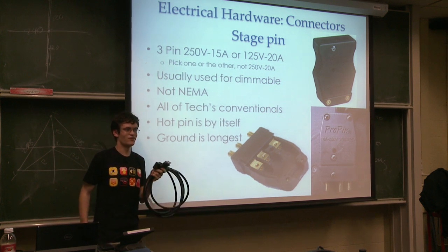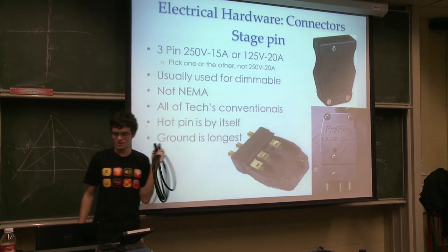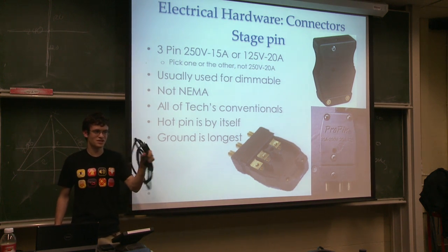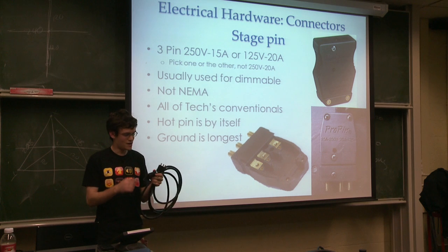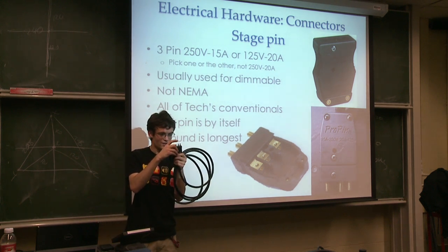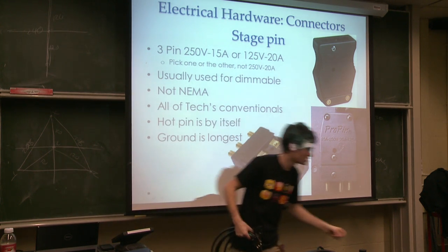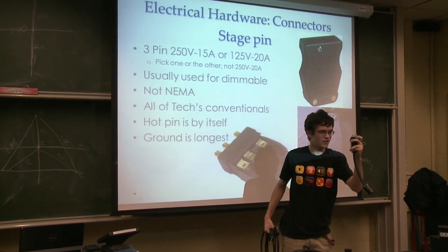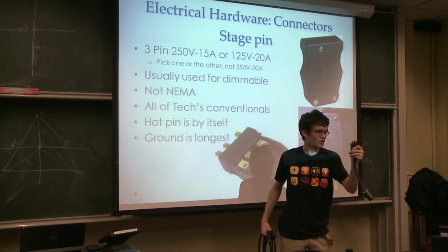However, it's fairly standard in the theater industry and entertainment industry. All of Tech's and Scotch & Soda's conventionals use this as their power connector. If you look very carefully, that one's actually not a good example. The ground pin is slightly longer than the others. Yeah, this one's good. You can see very carefully the ground pin's slightly longer. It's also in the middle.